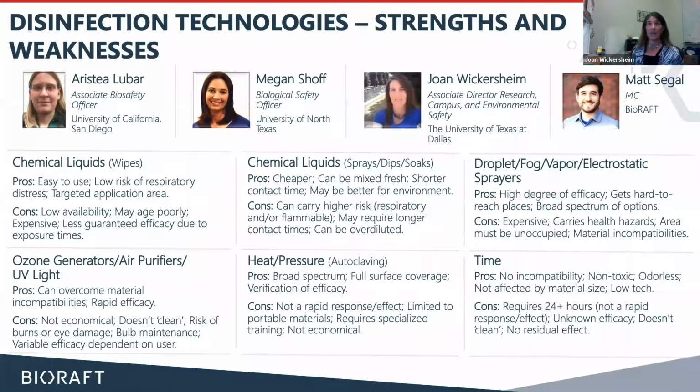No, we run it 24/7, full speed. And so sometimes increasing the MERV filtration rating is putting too much pressure on our systems. So for them, giving them the option of UV to help combat some of that, if we can't increase the filtration, perhaps we can just decrease the load going through the building. So, yeah, we updated our filters as well.